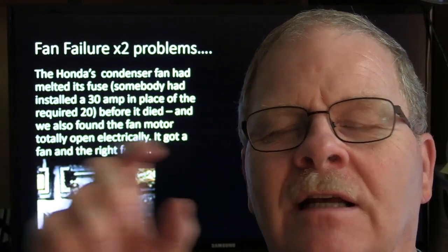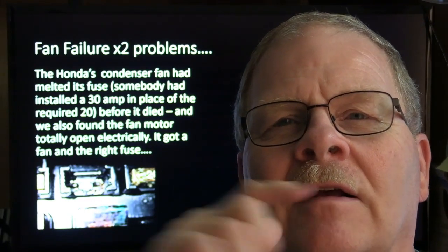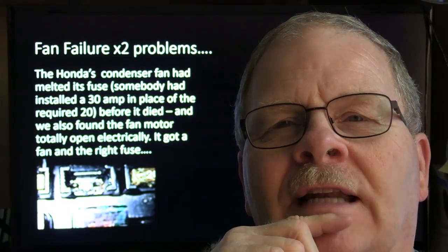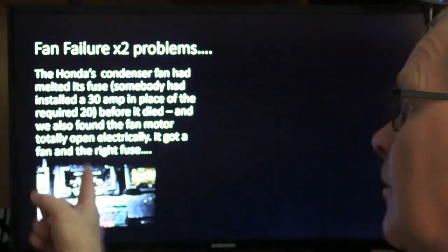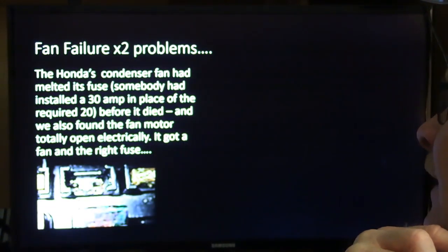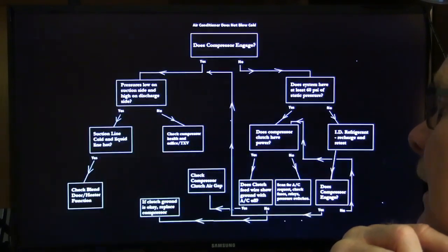clean that oxidation, and then use some canned air and maybe just a little shot of electrical contact cleaner to wash that off, to make sure that you didn't build up oxidation and resistance right there and have an issue like that again.